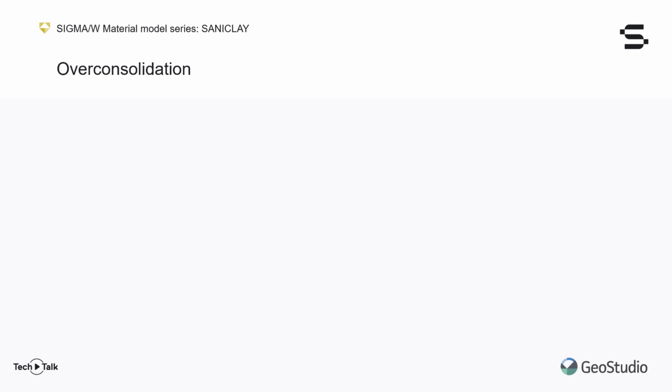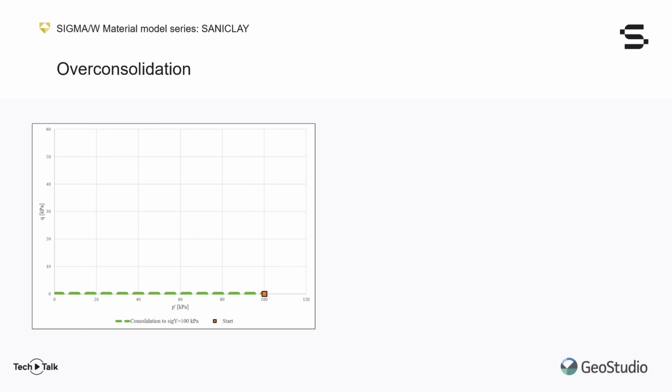Another important topic of interest relating to consolidation is, of course, over-consolidation. Consider here the endpoint of our isotropic consolidation stress path as the new starting point for an unloading phase, so that over-consolidation is created. If we relax the vertical stress applied on the sample, the mean effective stress will decrease. The over-consolidation ratio, OCR, is then the ratio of the maximum and current mean effective stresses.